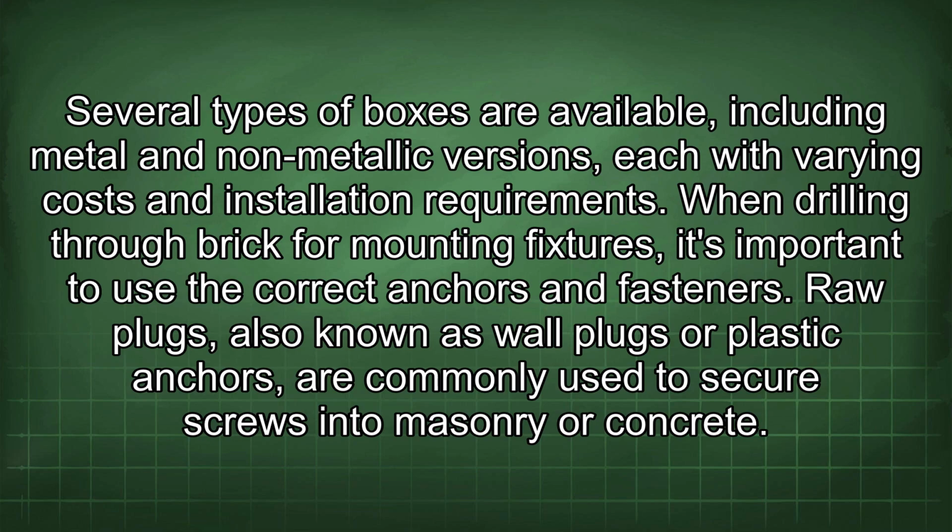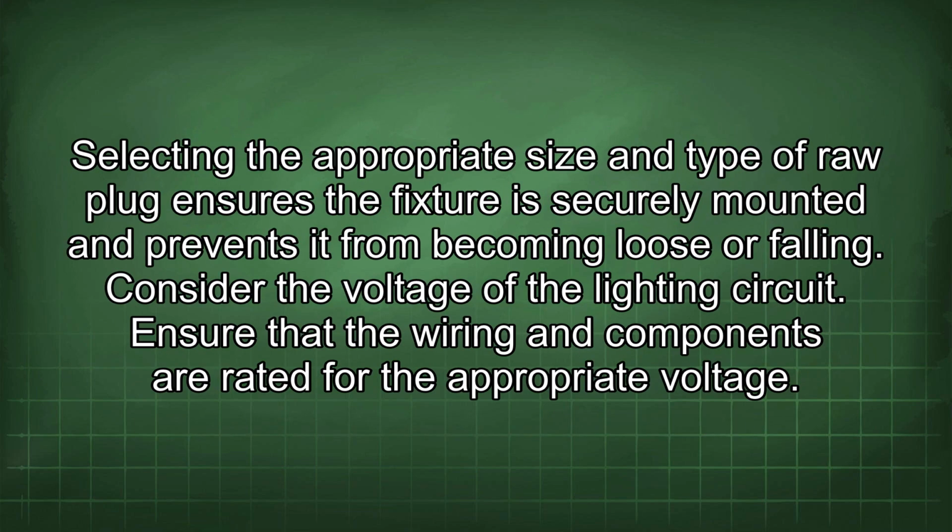When drilling through brick for mounting fixtures, it's important to use the correct anchors and fasteners. Raw plugs, also known as wall plugs or plastic anchors, are commonly used to secure screws into masonry or concrete. Selecting the appropriate size and type of raw plug ensures the fixture is securely mounted and prevents it from becoming loose or falling. Consider the voltage of the lighting circuit.